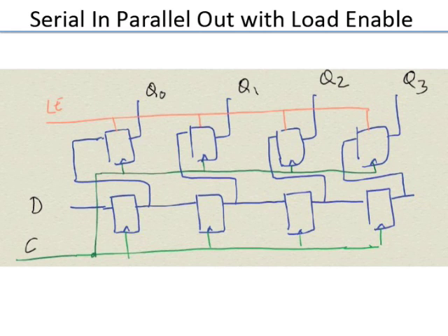For example, one of these bits could be controlling the power down signal of some piece of logic. Maybe you have some analog circuitry, and there is a bias. Bias enable is controlled by one of these things. So you want to change states from one state to another, but without shutting off the bias enable, because you want the circuitry to be on, but you want to change the configuration. So this gives you that protection, because you go from one valid state to the next valid state.